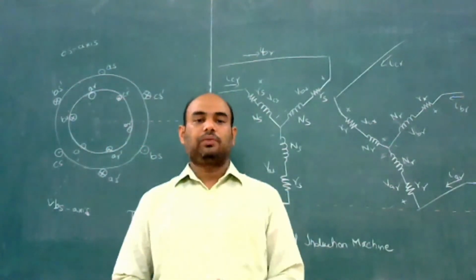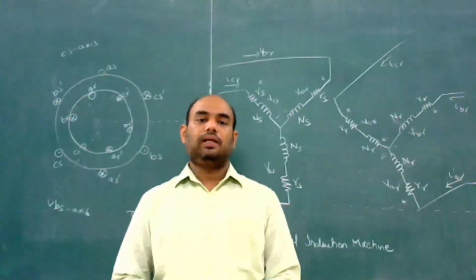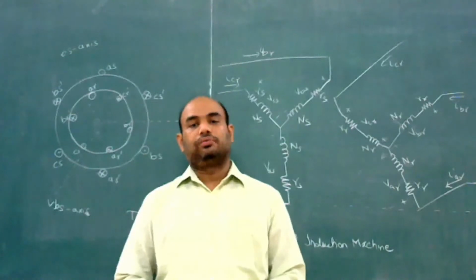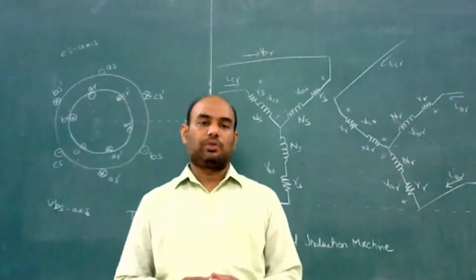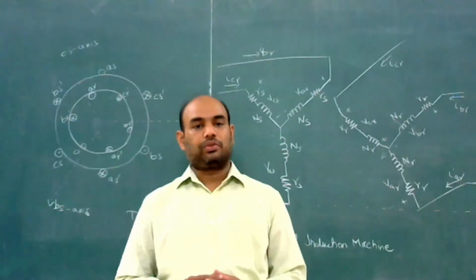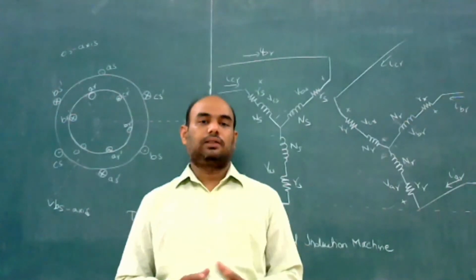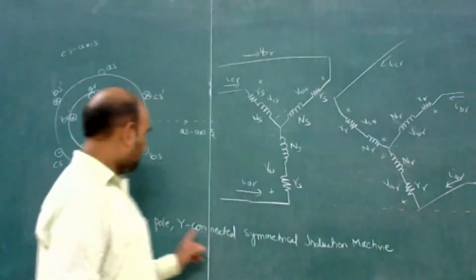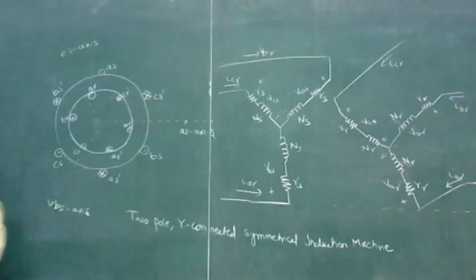Good afternoon, everyone. Today we are going to study the flux linkage equations of the stator and rotor of an induction motor using DQ transformation, or Park's transformation. Let us consider a two-pole star connected symmetrical induction machine. This is our stator.